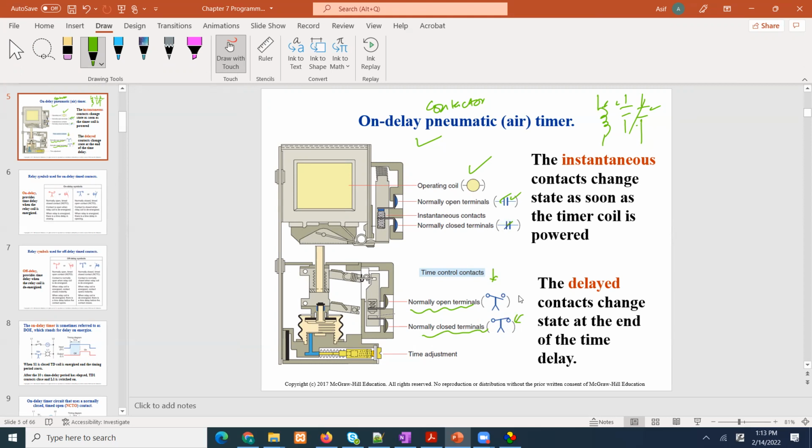This is normally open and this is normally closed. And the representation, so if I use, again, that idea I told you guys. If I use this contact, this is open and this is what? This is closed. So 0 and 1 will give me an energized output, yes? But if I use this guy and this guy, then it will give me what? Then it will give me off, yeah? Because it's 0 and 0.